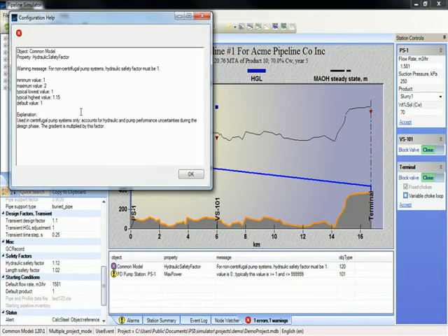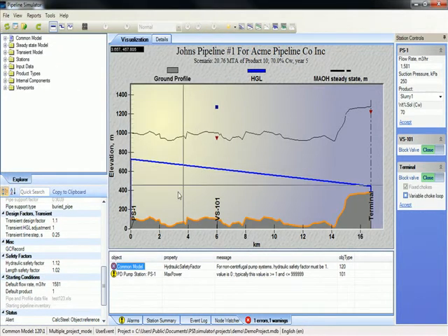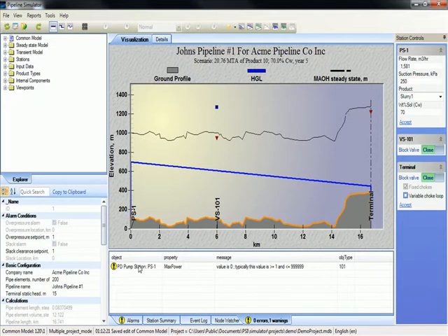Well, my error message said that this is for a centrifugal pump system only. Well, I have a PD pump system, so that's obviously a mistake on my part. So I'm going to put the 1 in there, hit enter, and you notice the error goes away. So that's how you use the configuration checker feature.